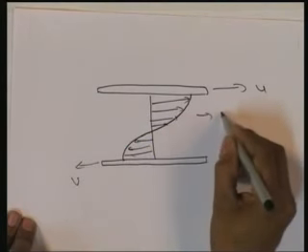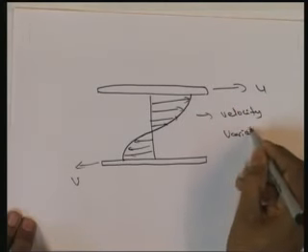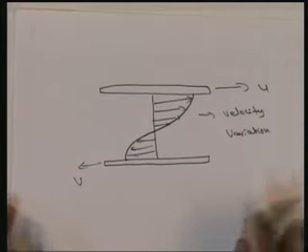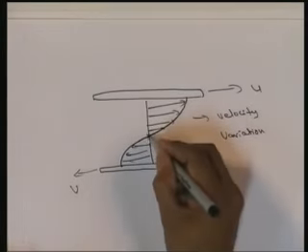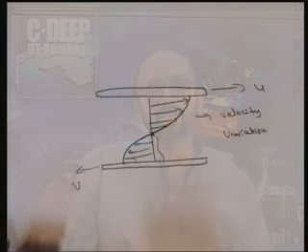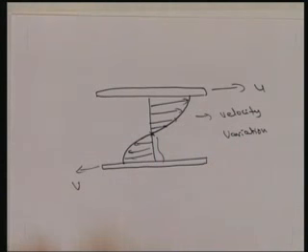So, this gives the velocity variation for this particular case whenever two plates are moving in the opposite direction. You can see that at this particular point there is a place where the velocity will be 0. You can just substitute velocity equal to 0 in the expression we got, and find the distance where the velocity becomes 0.